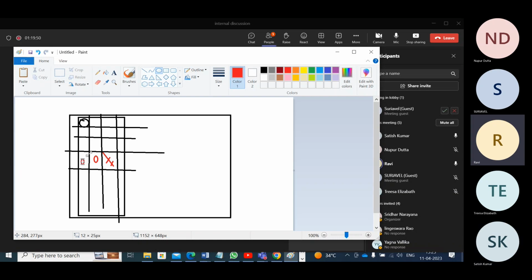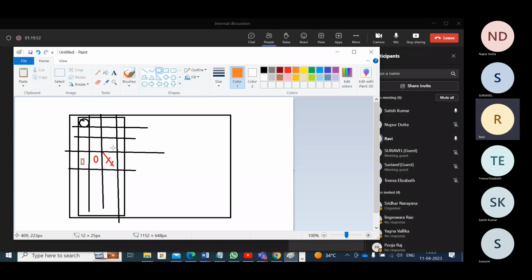The first way is it will place half the cells on the right side, half the cells on the left side. The nets are already connected, right? From the netlist, it will compute the total net length. Then it will say, if I move this cell from this axis to this one, will my net length come down, because there are other nets connected? If yes, then move the cell. If no, keep the cell.